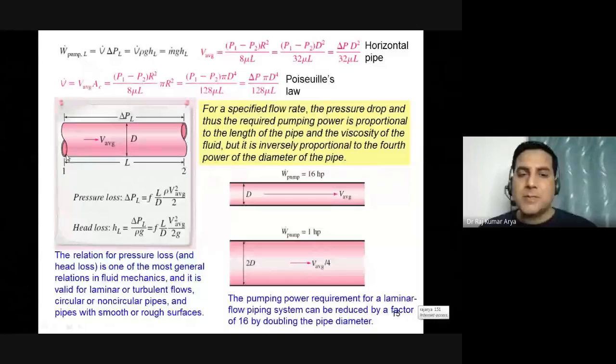Okay, the same thing happens for a pump also. Whatever energy you are supplying by electrical means, first the electrical energy is converted into mechanical energy. So there is some conversion efficiency. Most of the time that converts to 70%. These days you have some efficient pumps, they convert up to 80%, not more than that. So 80% of total, let's say your capacity of pump is 1 kilowatt. So 80%, that is 0.8 kilowatt, is converted into mechanical energy.